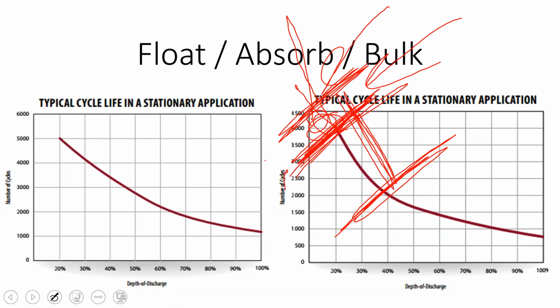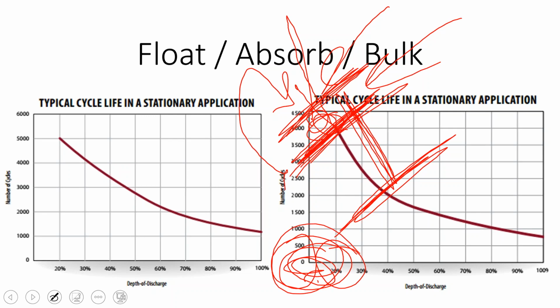You can put all that energy in to charge the batteries up to the top, but when we talk about a 48-volt battery bank, those batteries are commonly rated for 60 volts and not 48. So they're designed to operate at 48 volts, but you could actually drive them all the way up to 60 volts if you had a lot of energy to do so.